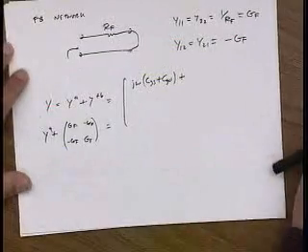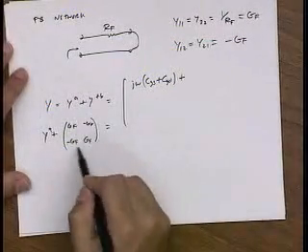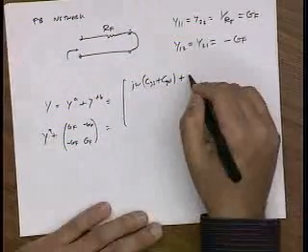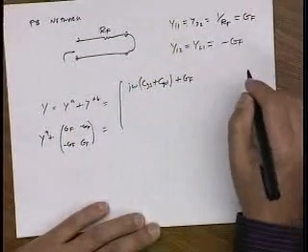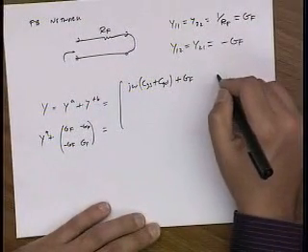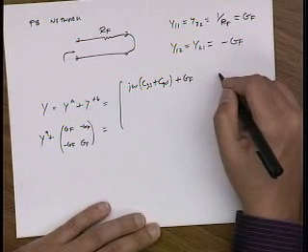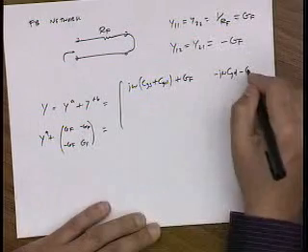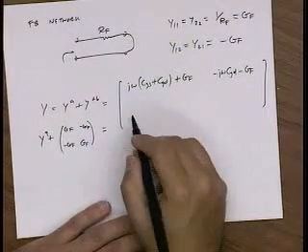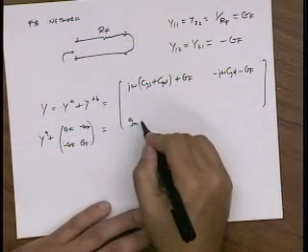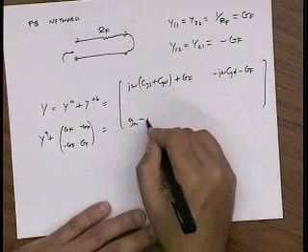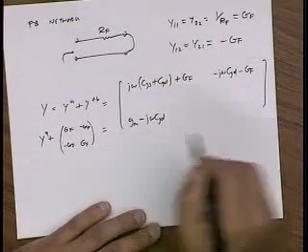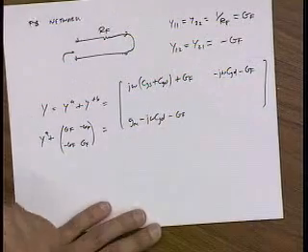We can just take the Y parameters of the transistor and add these 4 numbers. So I get a GF here. Here the Y parameter for the transistor was minus Y mu, so it's minus j omega C gate to drain, and now I also subtract a GF. Y21 of the transistor was GM minus j omega C gate to drain, and now I also subtract out GF.